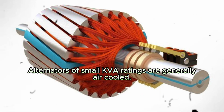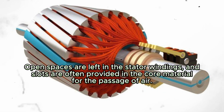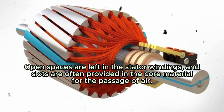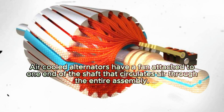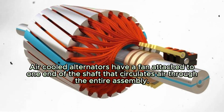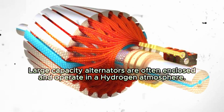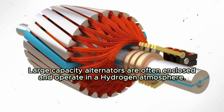Alternators of small kVA ratings are generally air-cooled. Open spaces are left in the stator windings, and slots are often provided in the core material for the passage of air. Air-cooled alternators have a fan attached to one end of the shaft that circulates air through the entire assembly. Large capacity alternators are often enclosed and operate in a hydrogen atmosphere.